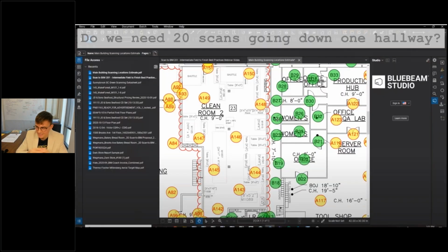All right, the second consideration. Is there enough overlap between scans so that the puzzle can be assembled afterwards? This relates to scan registration. That is, once you've collected all this data, will you be able to figure out how it all comes together into one coherent representation? I talk about this process more later on, but understand that overlap between scans is really important for this.